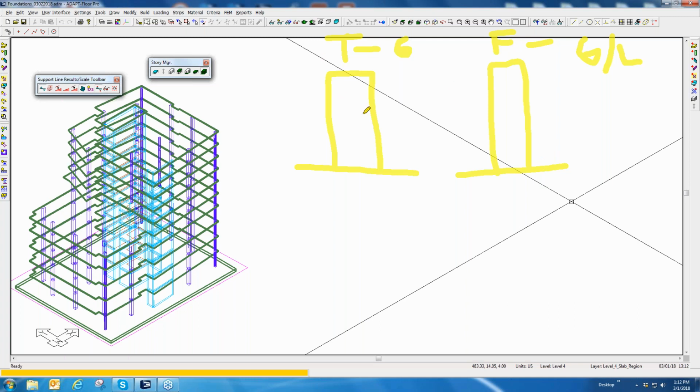So the nice thing about this is when we do this method and we get reactions down at the base, or we do this method and we get reactions, we might get shear and we might get moments at the base in these columns or walls. We have the ability to decide or to envelope which reactions we want to use and apply to this base. So the first thing we have to do is generate tributary load takedown, and run the model globally to obtain a solution. And like I said earlier, we've already done that for 3 different usage cases.